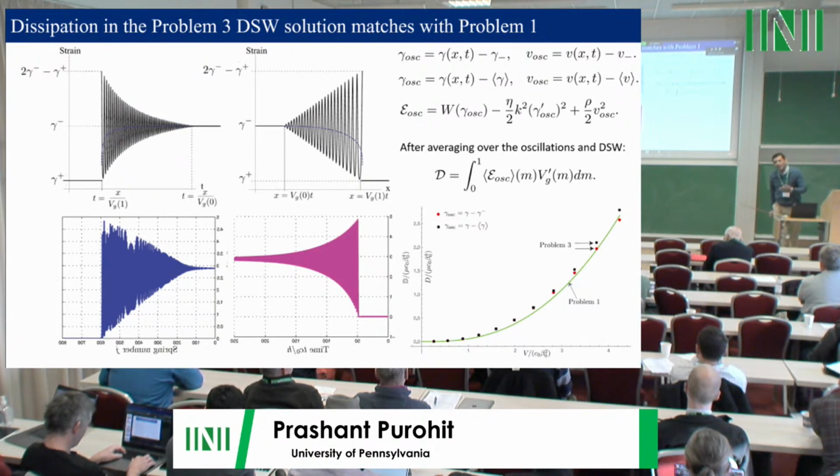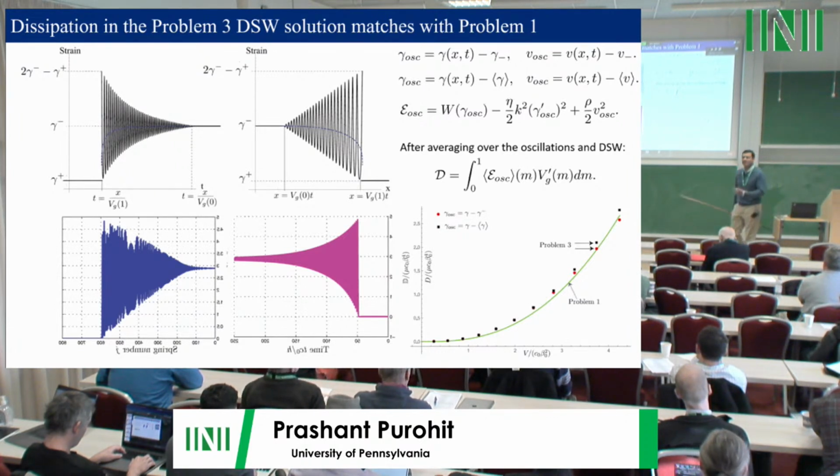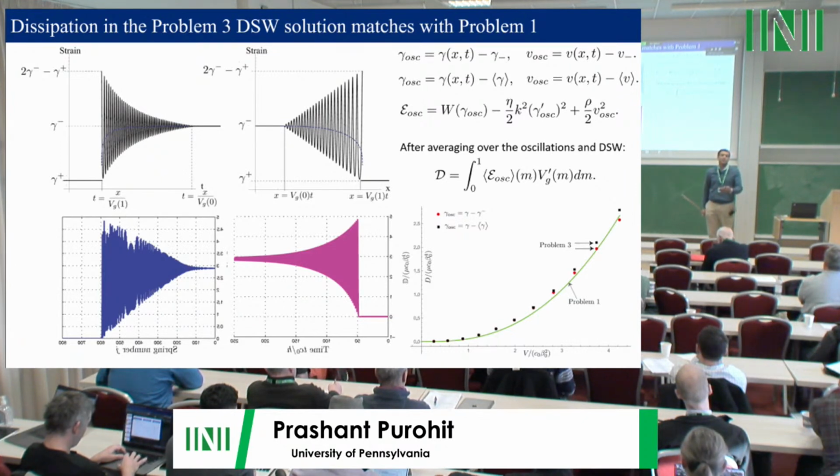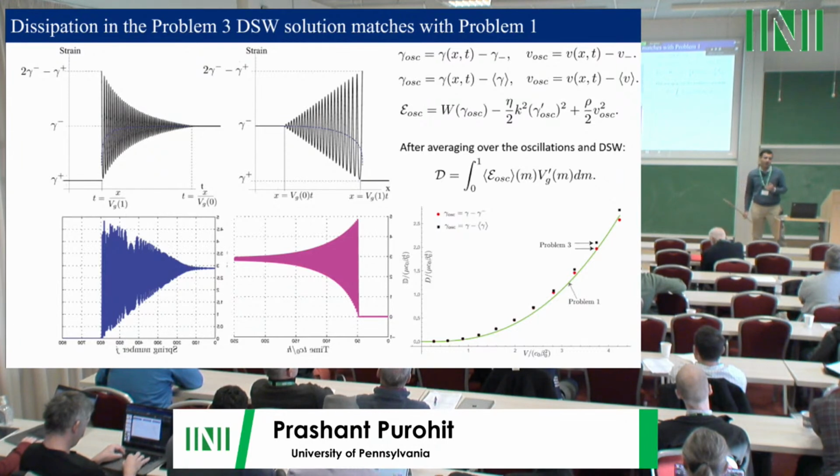So this time what we have been able to do then is we have been able to show in a quantitative way that the dissipation that is occurring behind a shock wave in an elastic bar, really all that energy is stored in these oscillations, and you can quantify the dissipation exactly so that you can compute the driving force across the discontinuity, and we know exactly where that energy is going.